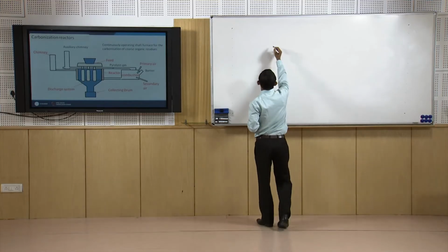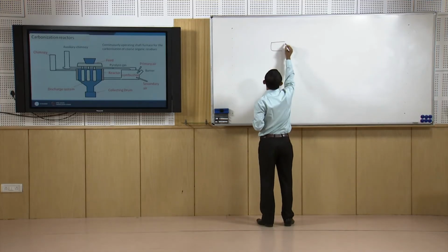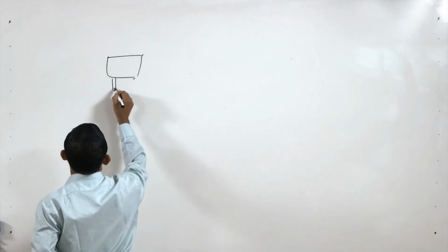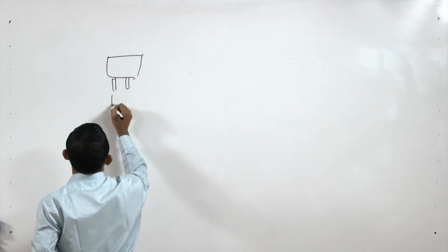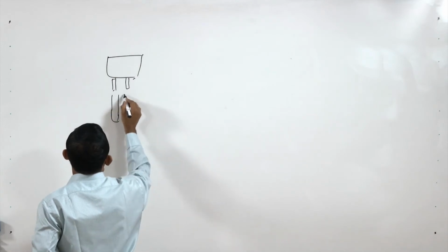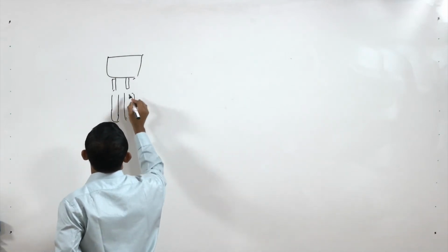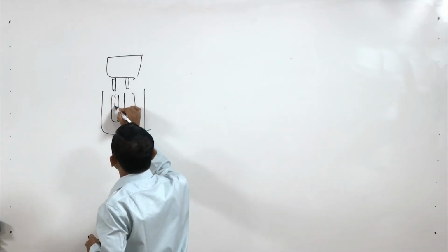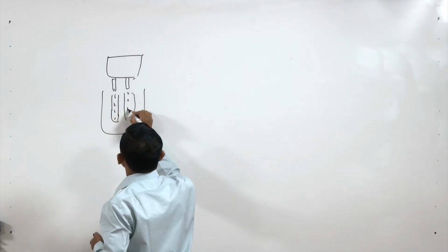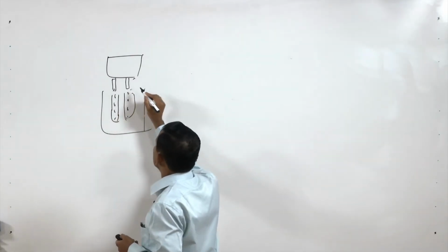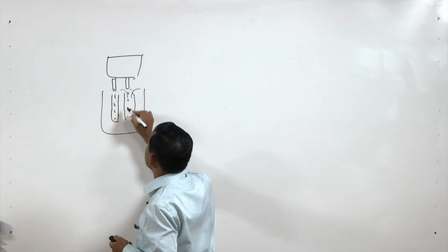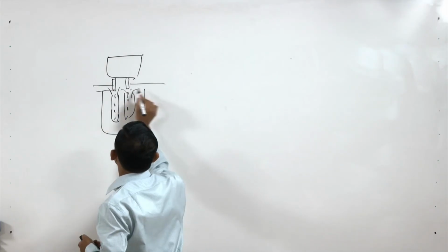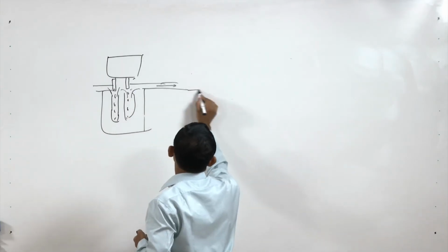Now, this is suitable for coarse materials; for fine materials it will not be suitable, because the material is fed through these channels. Bigger size materials will flow inside, but the off gas generated during heating also goes off through this channel and back to the combustion chamber.